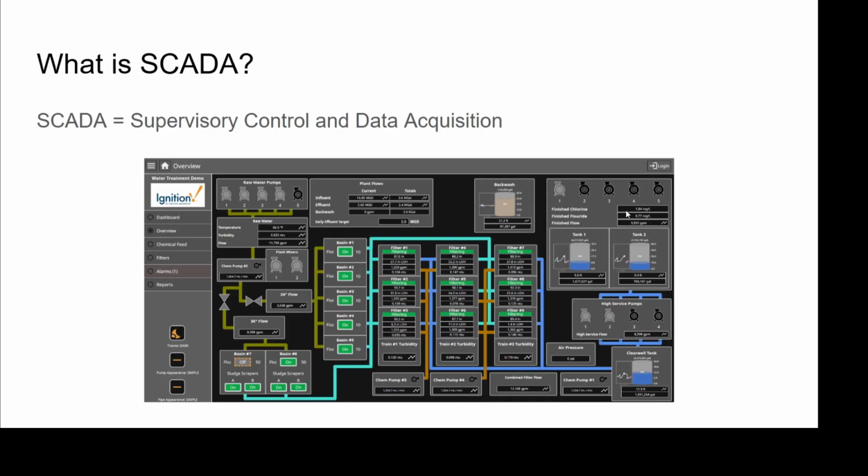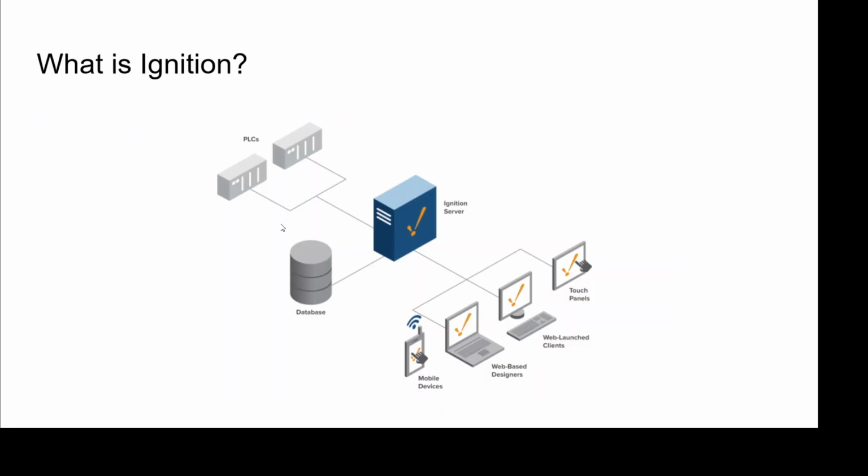We could also say, let's say we want to get a certain flow through our raw water pipe. Maybe we want to get 12 gallons per minute instead of 11.7 here. The PLC would then tell these pumps either to speed up or to start an additional pump to meet that flow rate, and then it would control the speed of those pumps to maintain whatever our set point is there. And that's all done in the logic in the PLCs, which kind of goes beyond the scope of what we're talking about in these videos, since we're focused on Ignition.